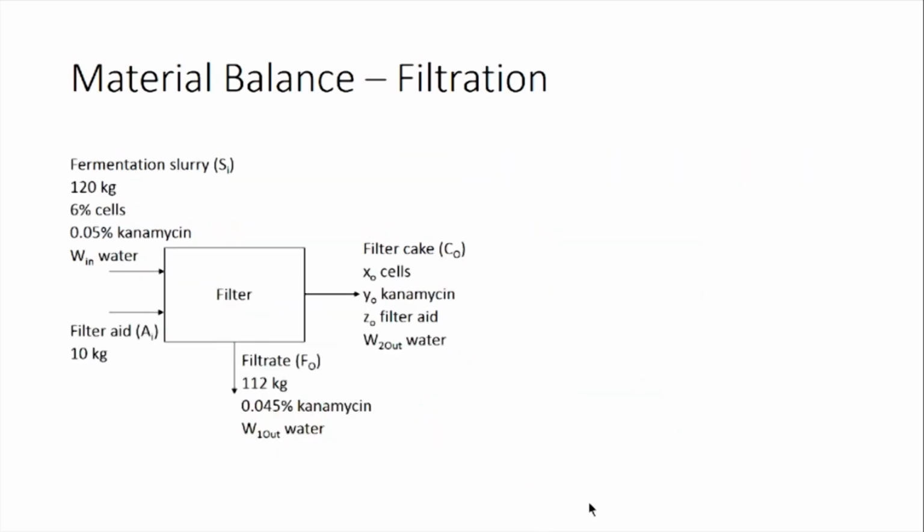Here is the flow chart which we drew, in more legible fonts. Now, let us start with the balance equations. The first balance we write would be the total balance. The total balance equation for this system would basically be input equals output, because it is a system in steady state leading to accumulation being 0, and as the system does not have any reactions happening, generation and consumption terms will also be 0.